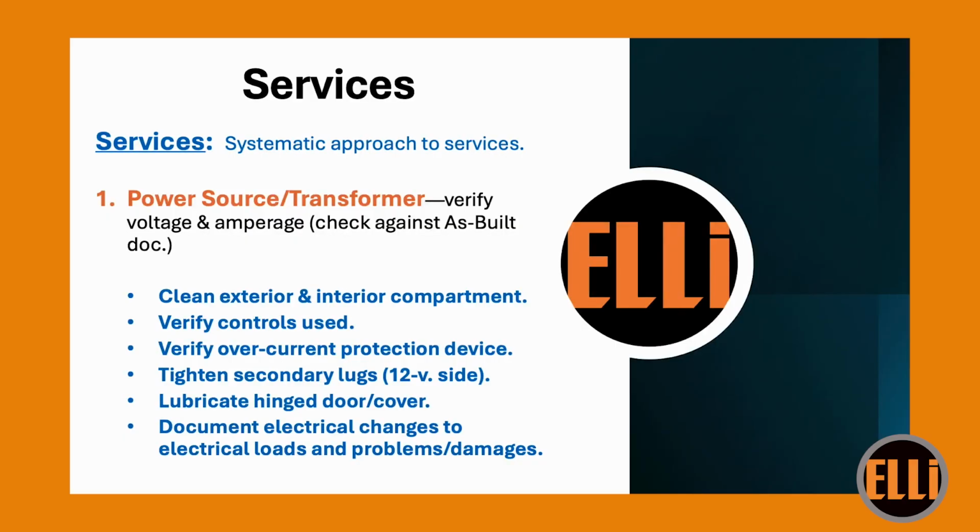And then part of the services here is you want to first clean the exterior and the interior compartment of the transformer, because it will be dirty, obviously. They're usually exposed to the outdoor environment, and there are ways for rodents and insects to get inside the transformer, especially if you're not using conduit to feed the cabling up inside the transformer.